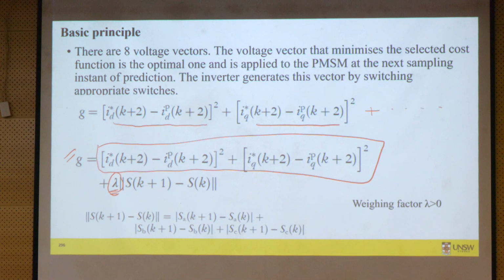And it is actually important to have switching loss minimization, because when we are using prediction, your space vectors could be anywhere in that hexagonal plane, right? So you may be turning on and off some switches unnecessarily.